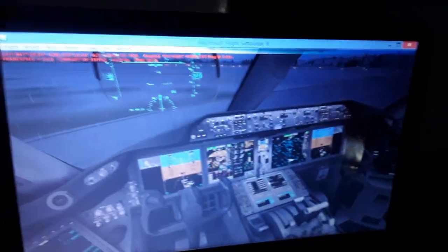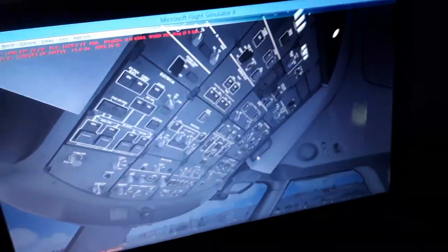which is the low speed low pressure compressor and turbine of the turbofan engine, exhaust gas temperature, N2, which is the high speed high pressure compressor and turbine of the turbofan engine, and fuel flow per hour, oil pressure, oil temperature, oil quantity, and vibration of the N2 states of the engine.